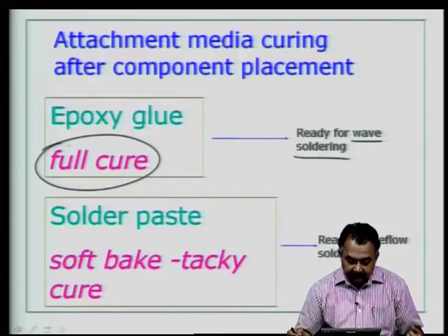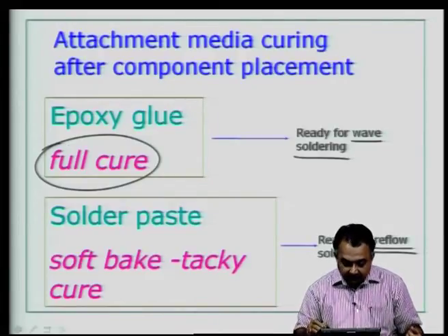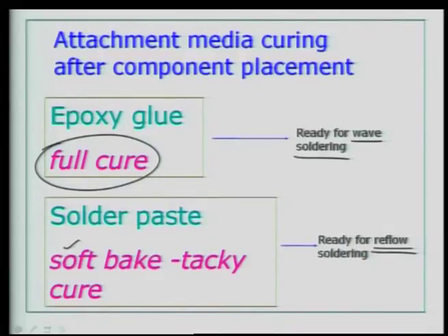In the solder paste application process for reflow, you will see that you have to use a soft bake, also known as a tacky curing process. Okay. So, you do not do a full cure here. The full cure will take place when the entire system is sent through the equipment during the reflow soldering process.